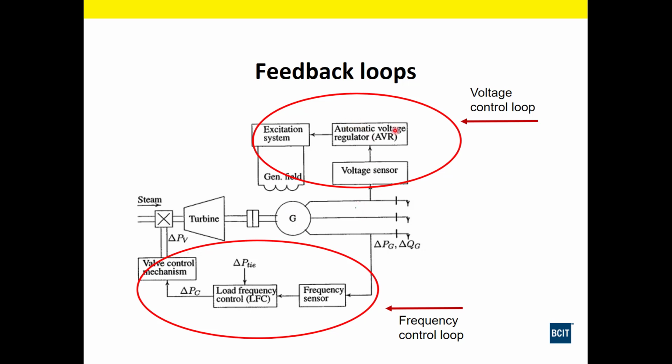Okay, and typically these AVRs are not going to run at exactly 600 volts or one specific voltage. They're going to run in a small range. So if it was a 600 volt generator, it could be bouncing up and down between 595 to 600 or 593 to 600. Typically, they don't want to go over voltage because equipment doesn't like it when you over voltage sometimes.